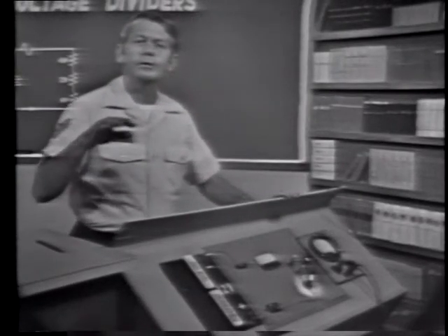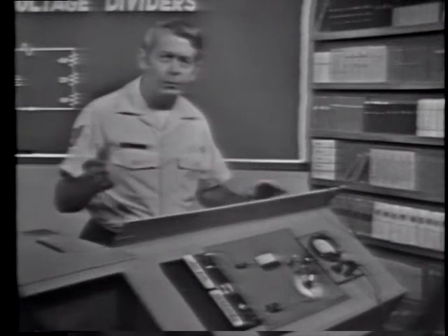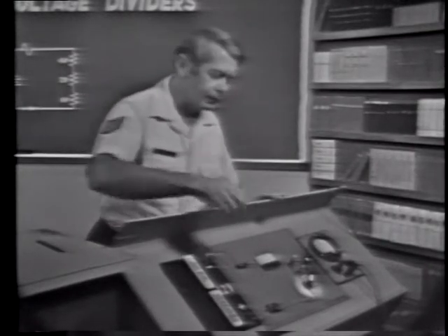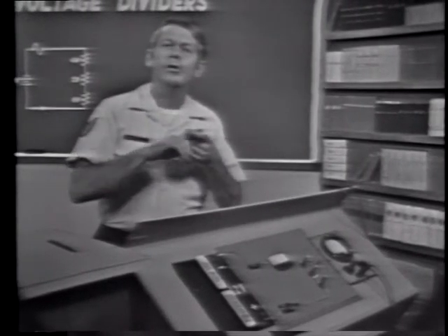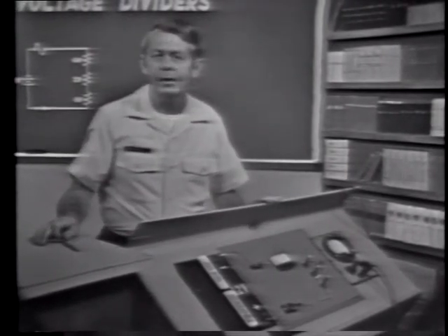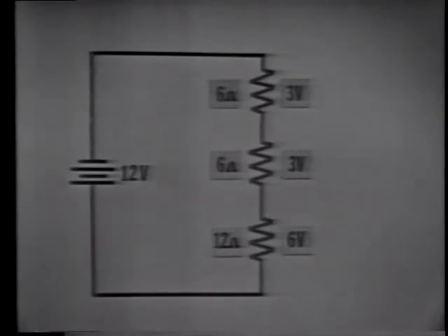Now, of course, if we load the circuit more, the voltages in the divider will change more. The important thing is the voltage divider is no longer providing the voltages we started out with. Let's use this diagram and we can see this a little better.